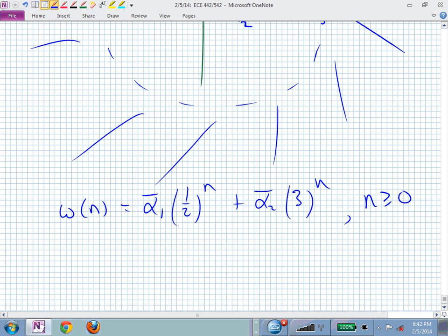It's something. And we know that we can directly add those because they're both on the same side of the region of convergence, right? There's no donut. So we don't have to worry about splitting this expression into a negative part and a positive part in terms of the time index. We know that the region of convergence contains a huge z, and because it contains a huge z, we know the negative time indices have to vanish. That's why we can say this.